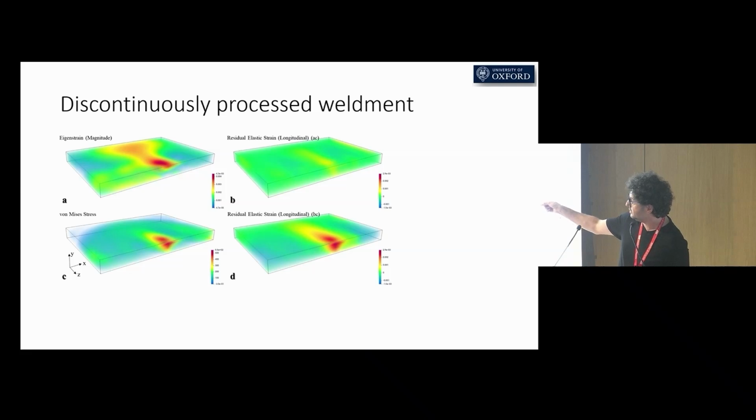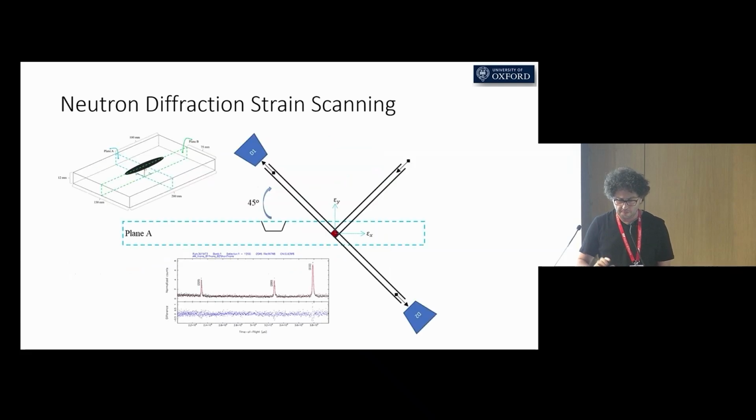Here we see the longitudinal component because we have the longitudinal component of data. We have displacements belonging to the z-axis. So these are the residual stresses parallel to the experimental data. And we look at the von Mises criterion. This is a nickel alloy, and magnitudes show that we don't violate the von Mises criterion.